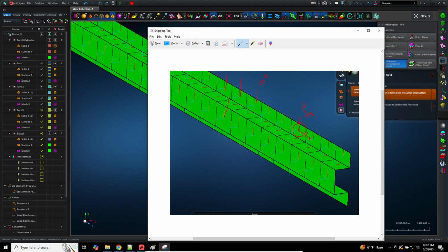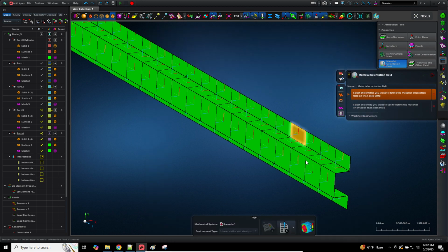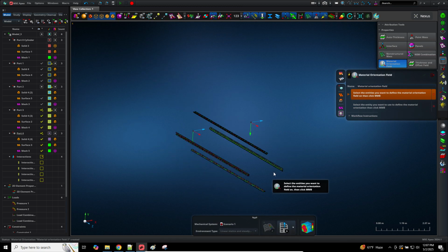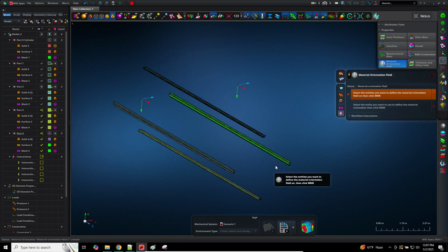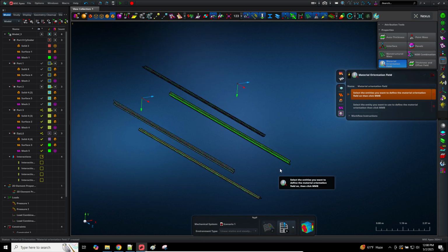But if you try to orient it in a different way, this element is completely wrong. Now, this is a problem because when you look at things like your applied stresses, the one direction for this element might be in this direction, but the direction for this other element is in a completely different direction. So it's very important that you know the 0 degree direction. Just to sum it up, sorry if that was a little convoluted.